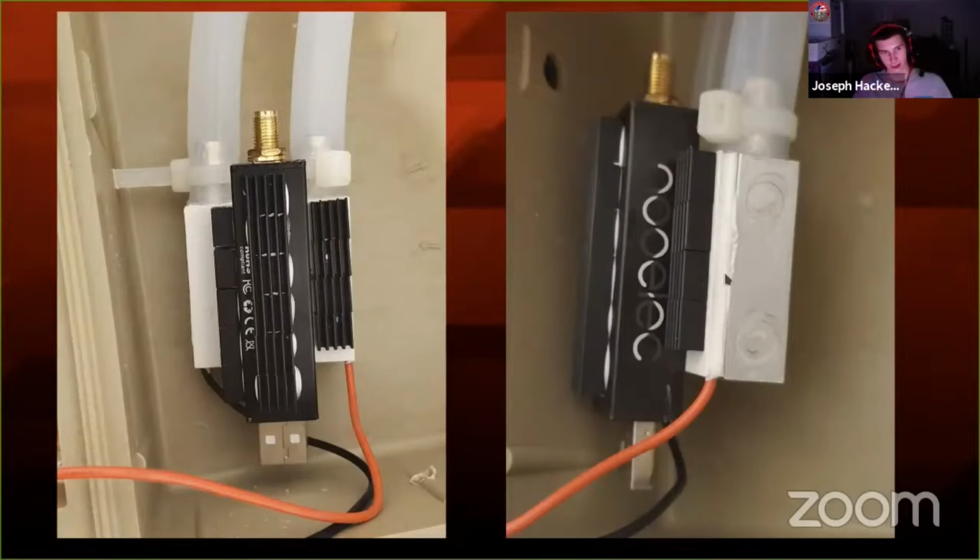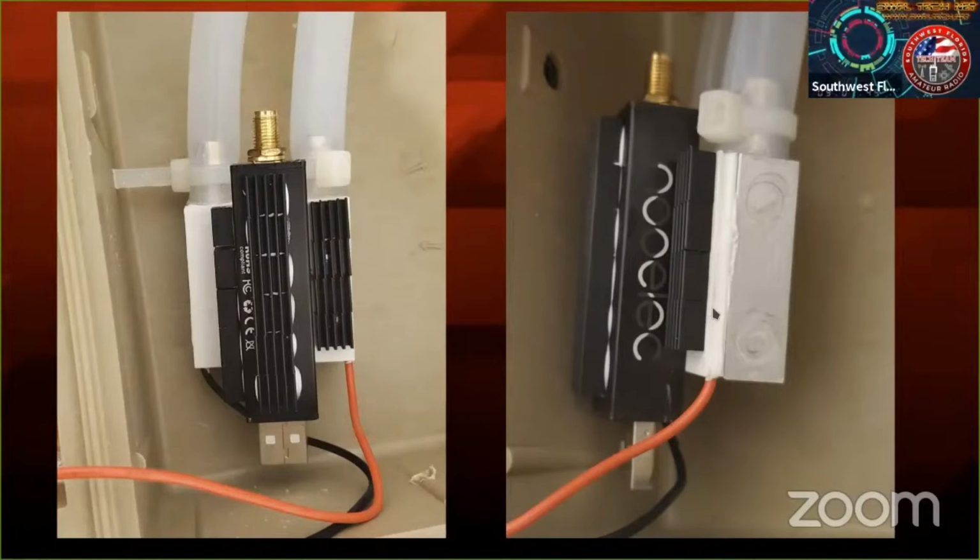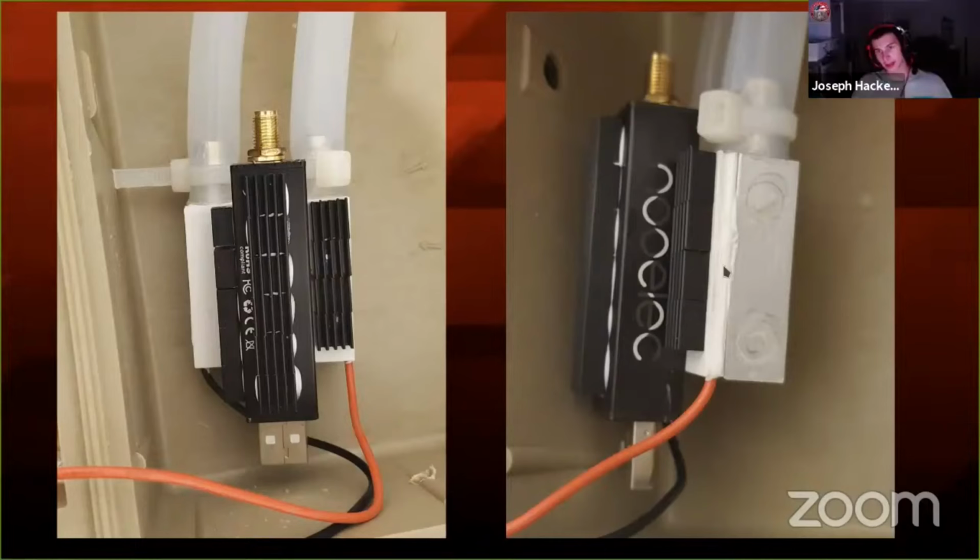Y'all see my cursor? I just want to make sure I can see my cursor on here so I can point at stuff. Anyway, it's not very big, but we can see it. The little white line here, that's the little Peltier, and when you give this thing 12 volts, it gets cold instantly, like ice cube cold on one side and fiery hot on the other. So what I've done is I've used thermal glue and attached one Nooelec RTL-SDR dongle to one side of it, as well as some little heat sinks. I guess you can call those cold sinks now.